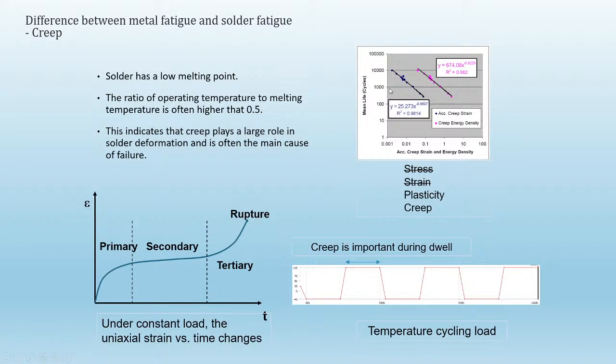Maybe somewhere in the hundreds of cycles, or if I use a very high reliability, expensive PCB, I can probably get into the thousands of cycles, and that's kind of the estimates you can get. If you want to be very careful and very detailed and accurate about solder joint reliability due to thermocycling, you need to add plasticity and creep.